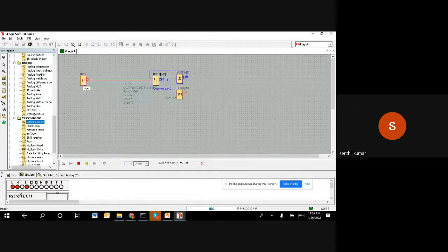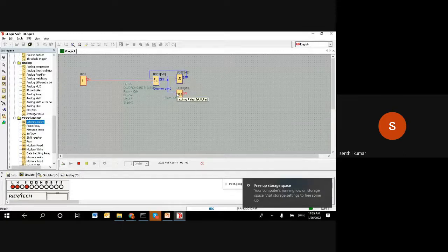So if you look at there, the output counter becomes 0, and then the output has become on, and then on has come and it reset. However, that one time on that has come, I latched. I could see, yes, it is confirming the on has come 1 pulse, which is a very short pulse, which is a millisecond, it catches the value. That's how it works.